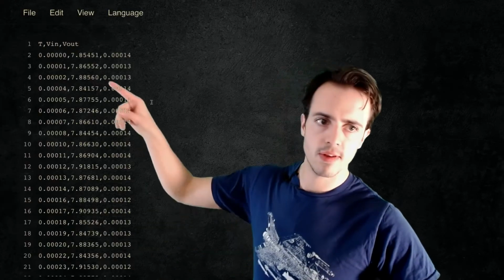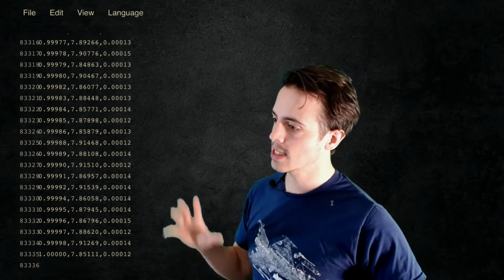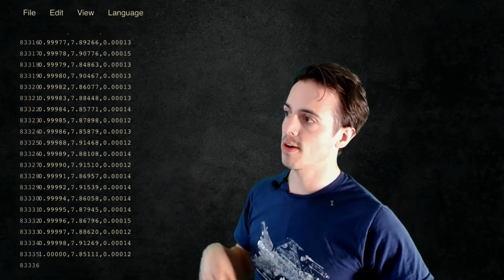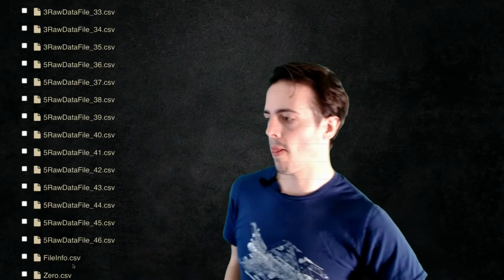We see we have time, V in and V out, and I think we've got about 83,000 of these measurements in each of them. Yeah, 83,000. I think this was 1 second's worth of data taking at 83 kilohertz. So we've got a lot of data here for each one of them. We want to do this data reduction to take these big data files and turn them into a single number from each of them. So let's close that. In here also we've got a 0, and we're going to talk more about what that means.